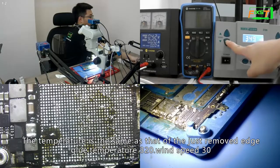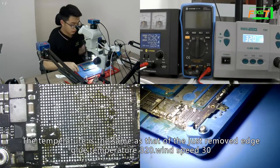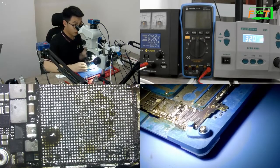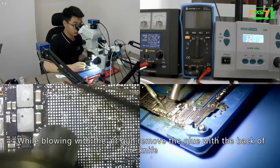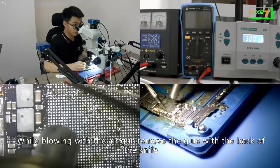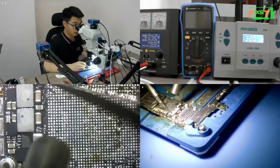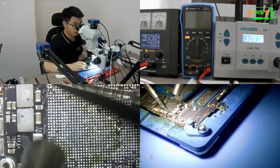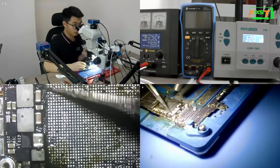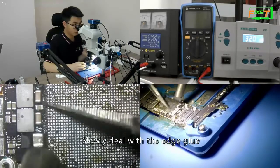The temperature is the same as for the edge glue just removed: temperature 320, wind speed 30. While blowing with the air gun, remove the glue with the back of the knife. Slowly deal with the edge glue.